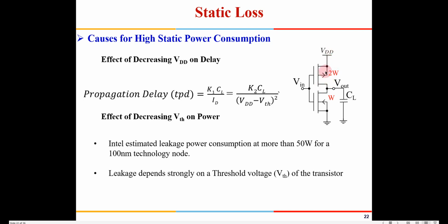It is because the MOSFET operation remains the same. Along with the device size being reduced, the voltage also is being reduced, so that the electric field remains the same, and hence the concepts of MOSFET operation remain the same.